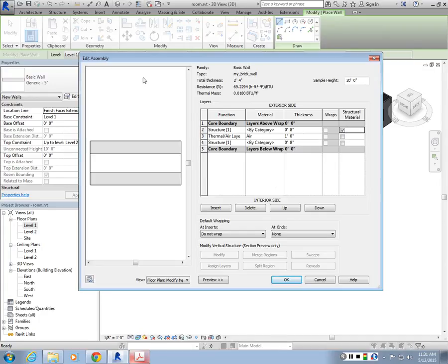Because don't forget, since this is object-oriented modeling, the information of each object we're creating is stored as data, right? So if I have, let's say, 30 rooms, and I want to know how many chairs I have in this project, I'll be able to document it through the file, because the file will keep all the copies of the same library instance.